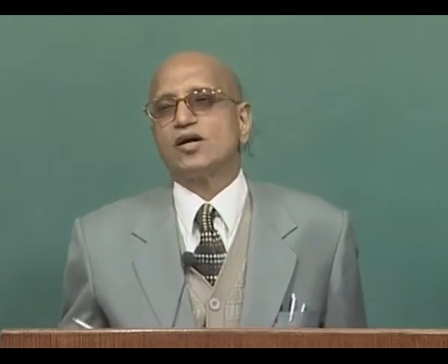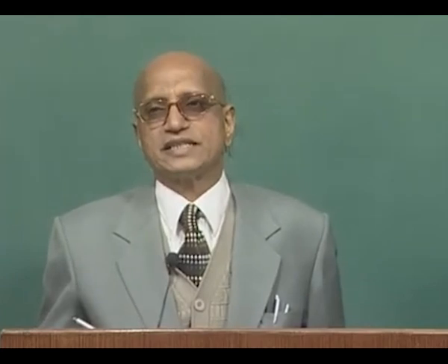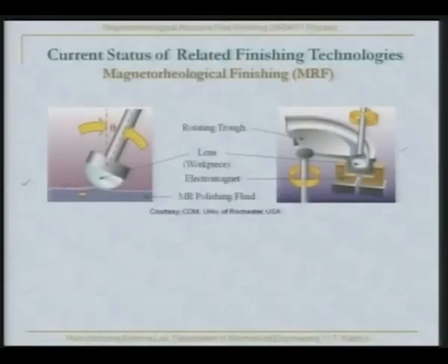Now, since irregularities of the lens can be represented as peaks of triangular shape, depending upon the depth of penetration and the axial force or the cutting force applied due to the rotation of this channel where the MR fluid is there, that will remove the material in the form of micro or nano chips.